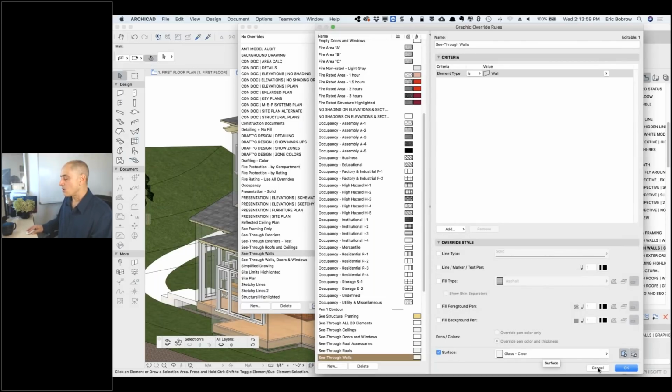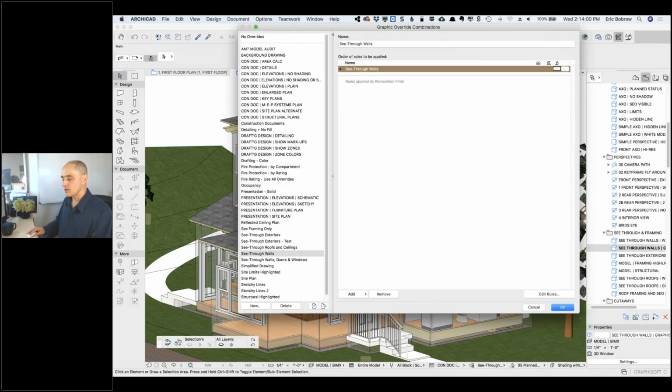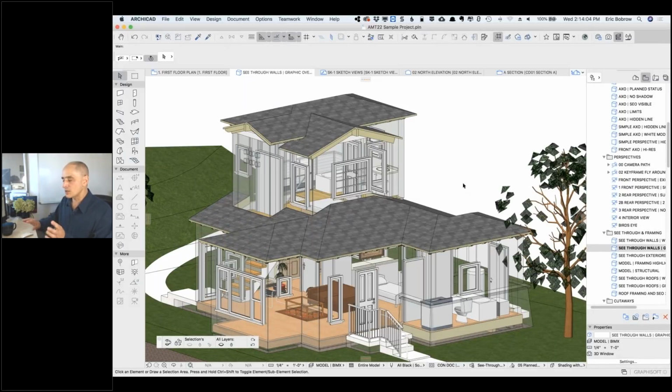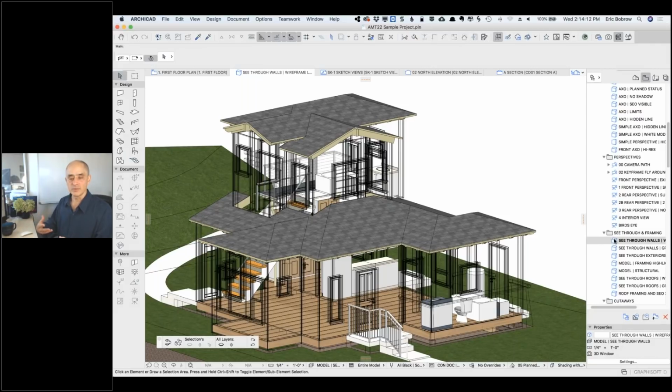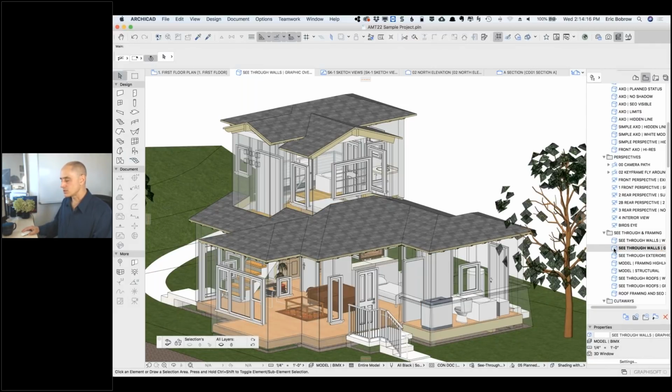All right. Now, I like it visually a lot. You can tell where the lines are, but you can see the doors and windows. It's a nice variation compared to this one. And I find this is sort of heavy, right? And this one is much lighter. Now, one is done with the wireframe layer, and the other is done with a graphic override, just with all the layers still showing normally here.